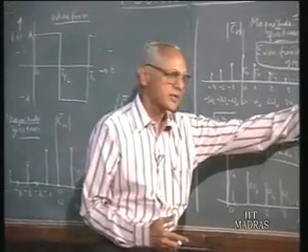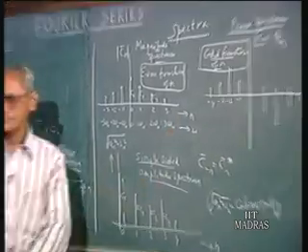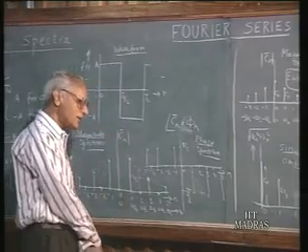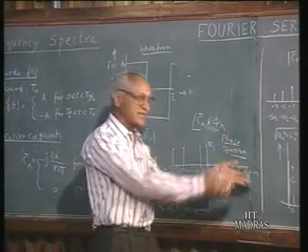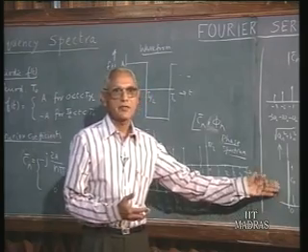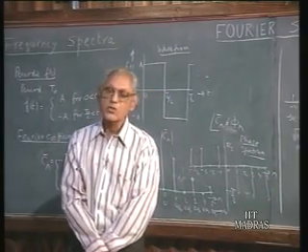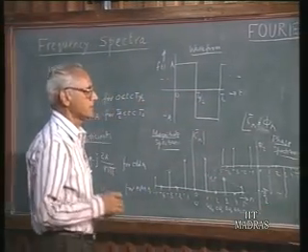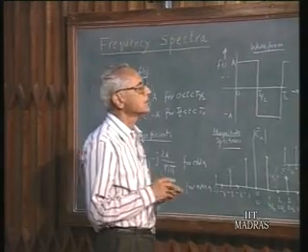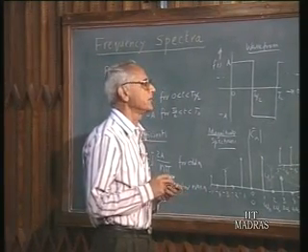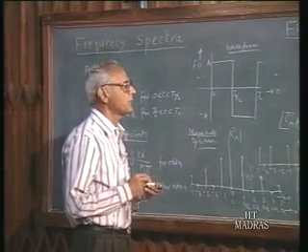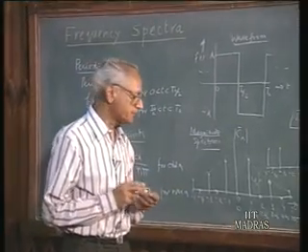So as far as the phase spectrum is concerned, you don't have any alternative. On the other hand, if you like, you can plot an and bn separately, but that is an unconventional way of doing it. Since each Fourier coefficient is specified by two parameters, we need two spectra, and usually we do this in the form of a magnitude spectrum and a phase spectrum.